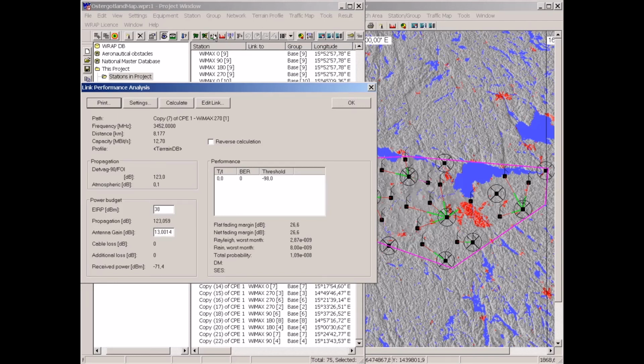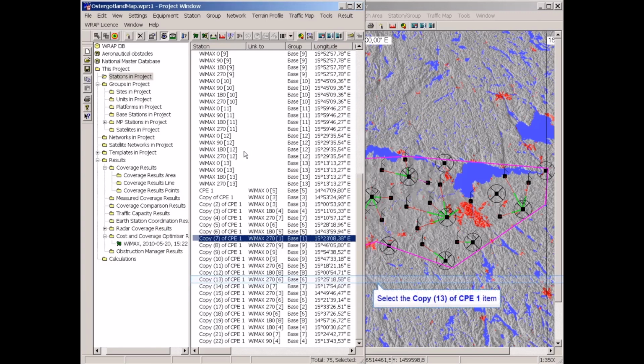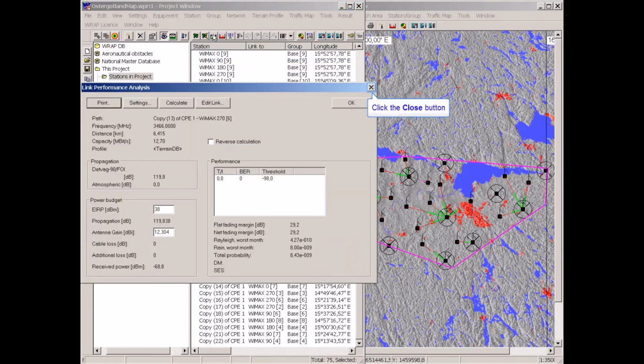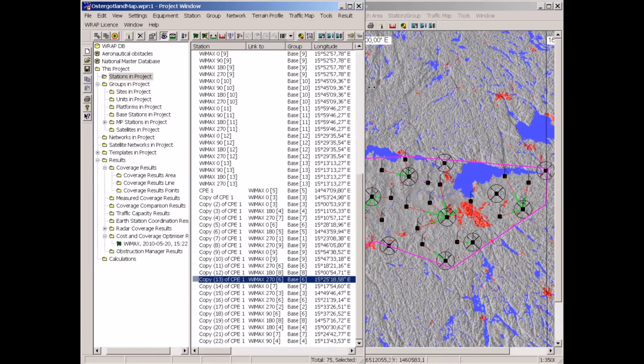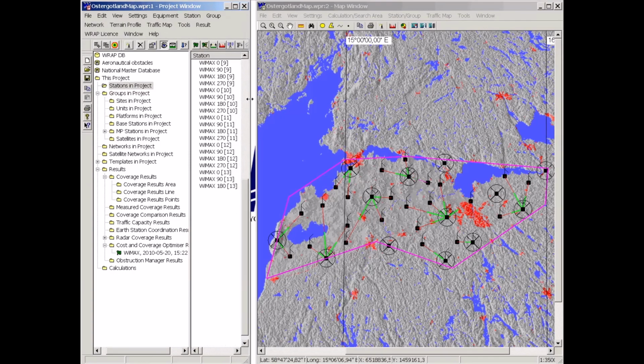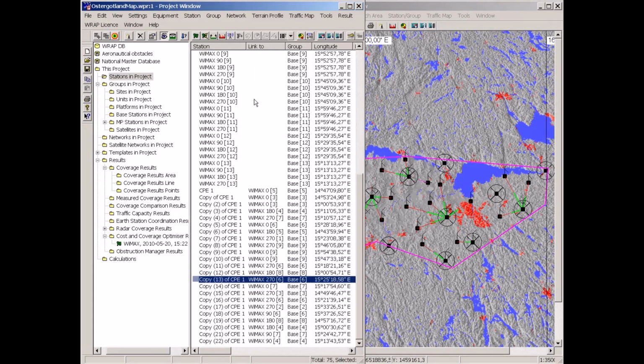And so on. Each of them should be okay because we have defined all the sensitivities accordingly and required 6 dB above sensitivity as the required signal strength. So all of them are okay, and the automatic linking worked the way it should.